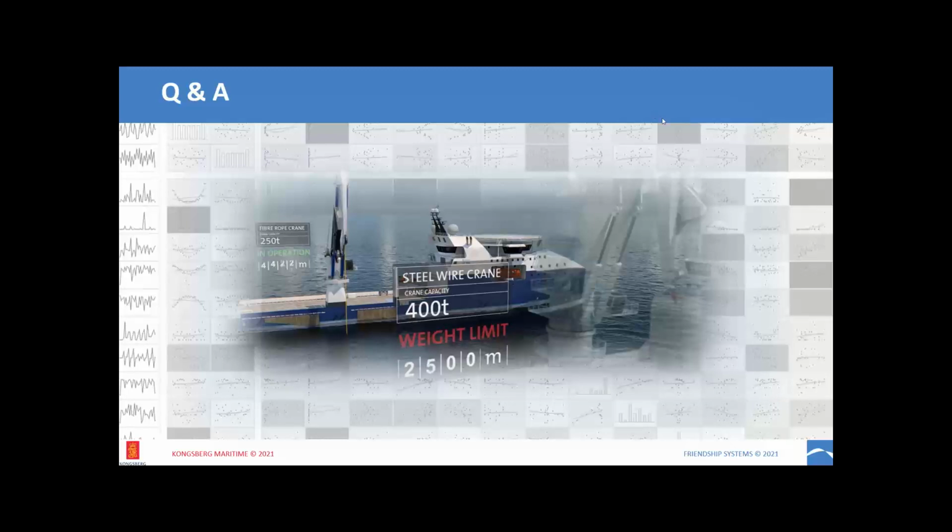Many of the projects are not interested in all the KPIs, the parameters at once, but very often we are interested mostly in, for example, motions on a specific vessel, and we just plug in the hull and run the motion calculation with this setup, or for resistance, in combination with DP resistance, something. So yes, the usage of this methodology is rising and rising.